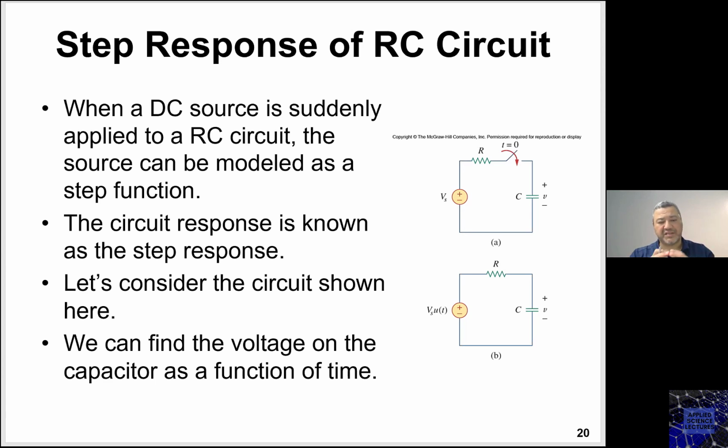Means that this is a steady state, which means capacitors are an open circuit, inductors are a short circuit, when the switch has been at this position for a long time, or under DC conditions.